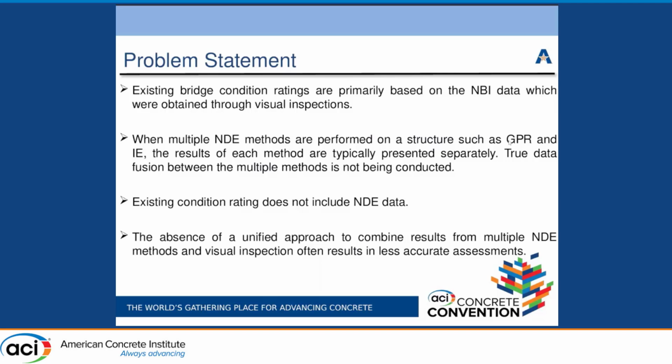From a survey that was conducted by the Federal Highway Administration, 10 state DOTs were consulted and they were asked how they use the NDE data. Even though the NDE data is very valuable because it gives you the condition of the bridge deck even before the external deterioration shows, many of the DOTs said they only use the NDE, but they don't incorporate that into their condition rating system. Also, there's an absence of a unified approach that combines both the results of multiple NDE methods and visual